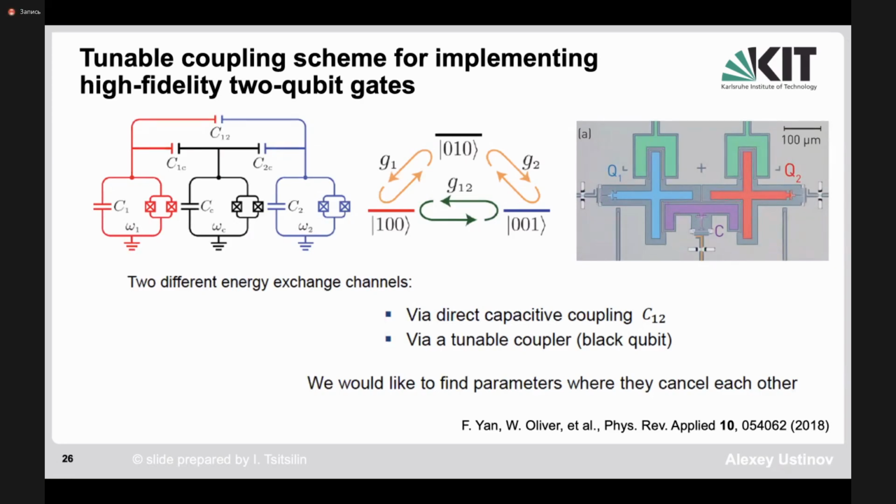So in a way, this coupling is a sort of negative capacitive coupling, or if you want, a coupling with a phase of pi between the oscillations in the qubits. Now imagine that you bring the circuit in the middle into resonance. You know that resonance means that the phase of the oscillations in the resonating circuit goes through a large phase shift exactly at the resonance.